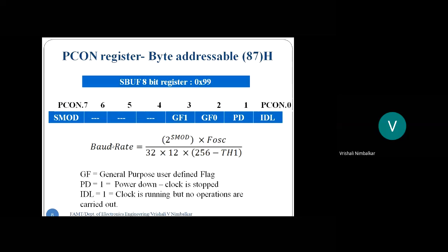Now see here, students, when we say we are having 8-bit data, we are going to store that 8-bit data in the SBUF register. Whereas the frame formation is done automatically internally by the microcontroller. That is, putting the start bit and the stop bit happens inside automatically.